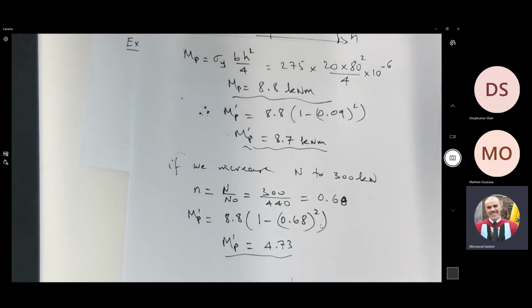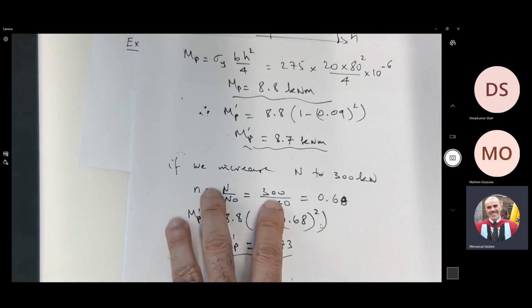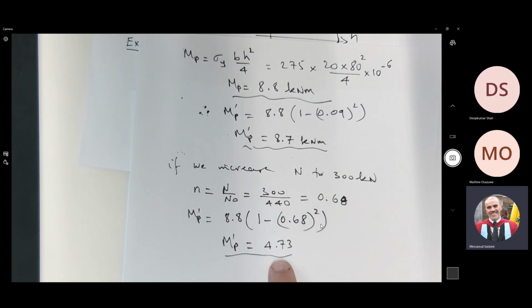If you think of a frame building, you haven't got just bending, you've got bending, shear, axial force, etc. Then you need to be careful when designing that you are not ignoring something that shouldn't be ignored, because it has an impact, as you can see here. It majorly reduces the moment. It's almost like a 50% reduction, which is quite significant.